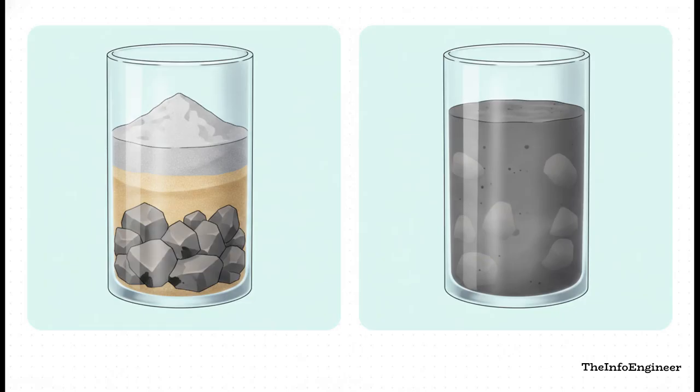To survive out there, you absolutely must understand the fundamental difference between wet volume and dry volume. Wet volume is your finished product. It's compacted, placed, and it's exactly what your formwork dictates after the water has been added and the mix leveled out. But dry volume? That consists of separate, loose materials that are full of empty air spaces. When you add water and start mixing, the finer particles like the cement and the sand rush in to fill the gaps between the larger rocks. The overall volume shrinks.